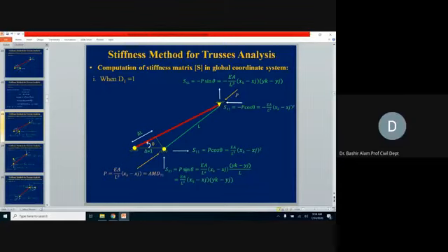Now, second, at the near end, if you see, S11 and S21 values are positive. So at the near end these coefficients will be positive, and at the far end they will be negative. So you can see here, negative and negative. So now we have generated the member force elements, and then the stiffness coefficient elements also.